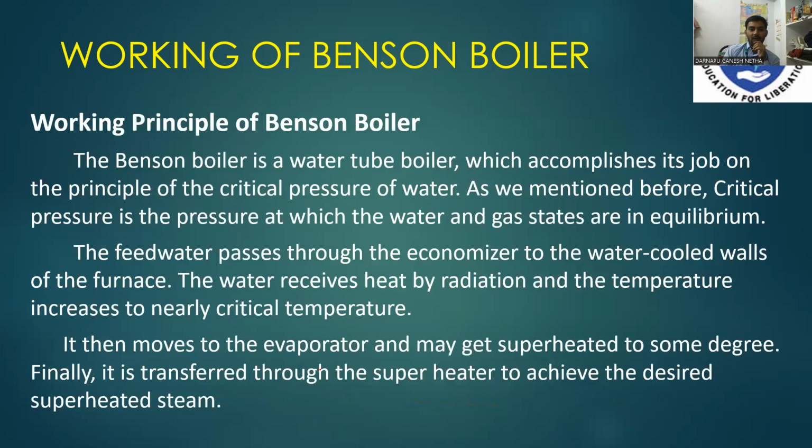Working principle of Benson boiler. The Benson boiler is a water tube boiler which works on the principle of critical pressure of water. As I mentioned before, the critical pressure is the pressure at which the water stays in equilibrium. The feed water passes to the economizer and then to the furnace.